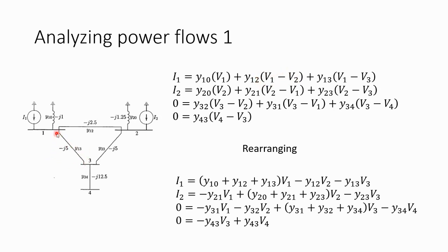The current on this branch is the difference between the potential of bus 1 and bus 3, multiplied by the admittance Y13. So now you notice, right? You notice the reason that we want to convert our impedance into admittance by taking the inverse of the impedance itself, so that we can avoid writing divisions on all these terms.